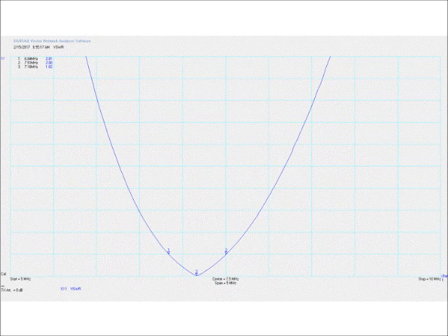In this case, for this antenna, this number is at 7.19 megahertz. This number is 6.54. This is 7.4. So the 2 to 1 SWR bandwidth of this antenna is about 1.5 megahertz wide, which, by the way, doesn't exist in the real world. That's quite an antenna. But these two numbers are at SWR 2 to 1, and of course this is 1 to 1. So how far they are apart is what's called the bandwidth of your antenna, the 2 to 1 SWR bandwidth.